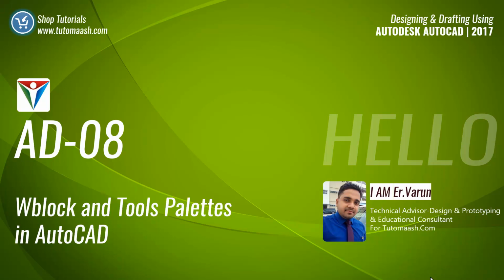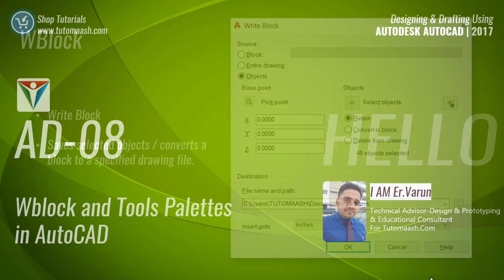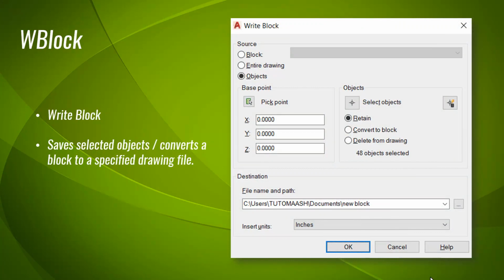In this session, we'll be discussing WBlock and Tools Palette. WBlock is the same as a block which we use in AutoCAD, but the only difference is that we can actually write the block, or we can say that we can permanently save the block which we have drawn. It directly saves the selected objects and converts them to a block in a separate specified drawing file.